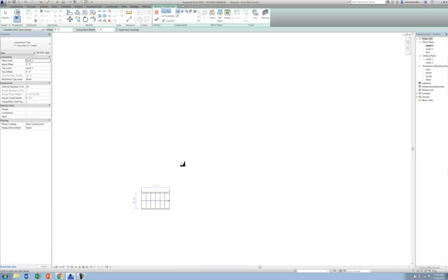It shows you how many treads you actually need to get to the next level and how many you've gone through so far. If you continue clicking to define more landings and more runs of the stair, you can see that it'll infer almost everything about the landings and railings as you go up. You can be really smart about how you use this. You can make pretty fantastic sets of geometry folding through space with a couple of quick clicks. That's not entirely what I'm going to focus on today, although I will show you how to adjust these.